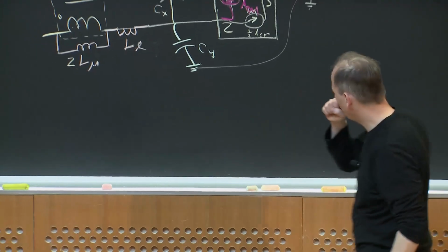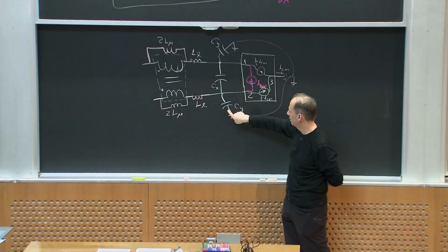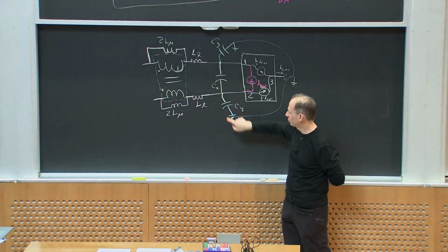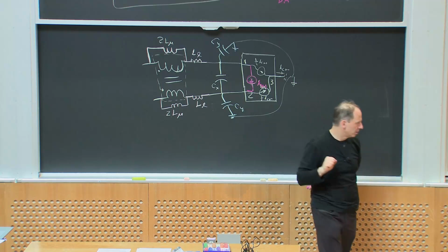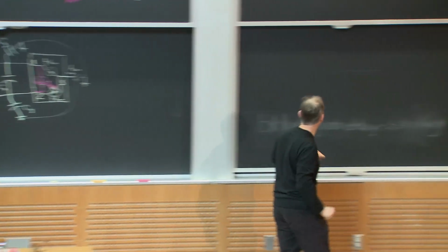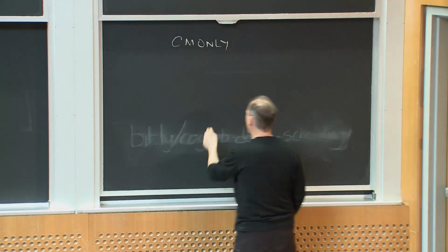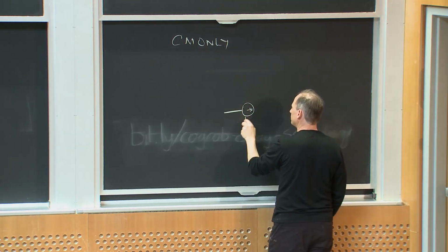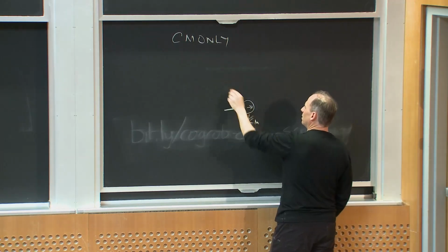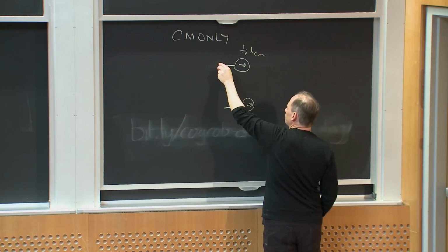Why? Well, I said if I wanted to kill the common mode component of current, I want it to cycle through CY. And my filter, then, if I were to redraw this, let me just consider the common mode components. So this is the CM only, okay, I have half ICM, half ICM.